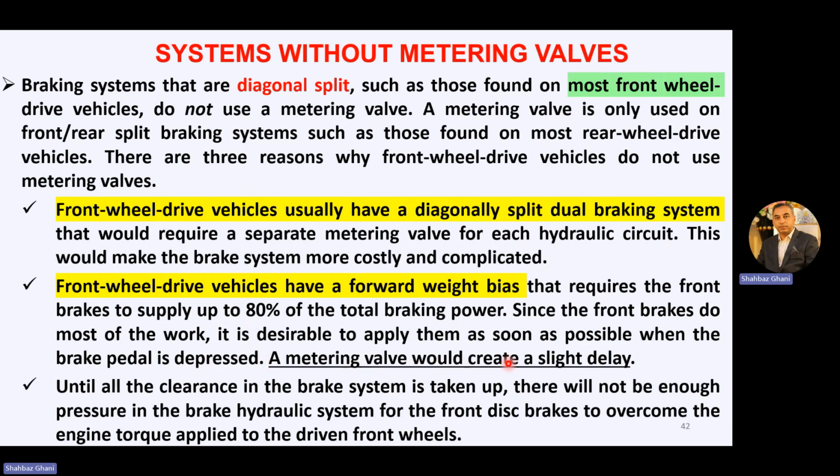A metering valve would create a slight delay or gap. So we do not use it on diagonally split, front-wheel drive vehicles.